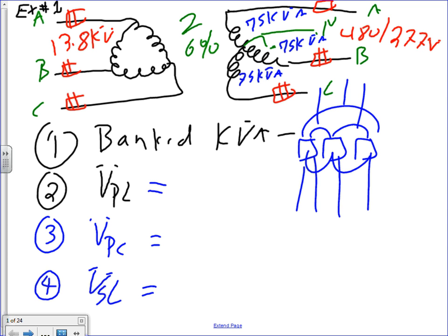So what you're looking at right now are 3 single-phase transformer barrels. Each one of them is 75 kVA. Cool? And they are hooked up to make a 3-phase system. That's one way of making 3-phase systems. This is not what we do in a commercial building. Typically in a commercial building, guys, instead of 3 pieces, all these will be in one big fat transformer.